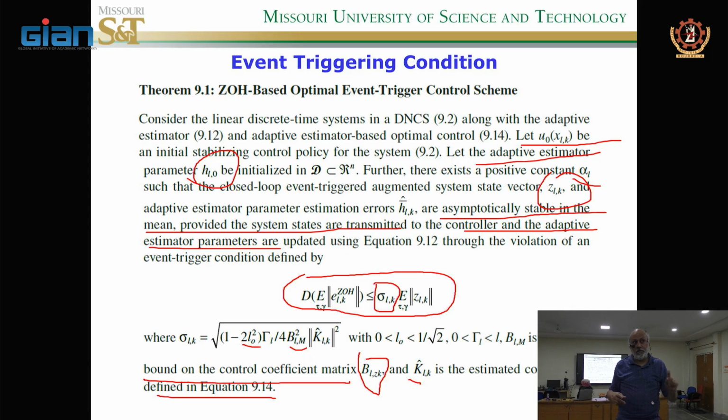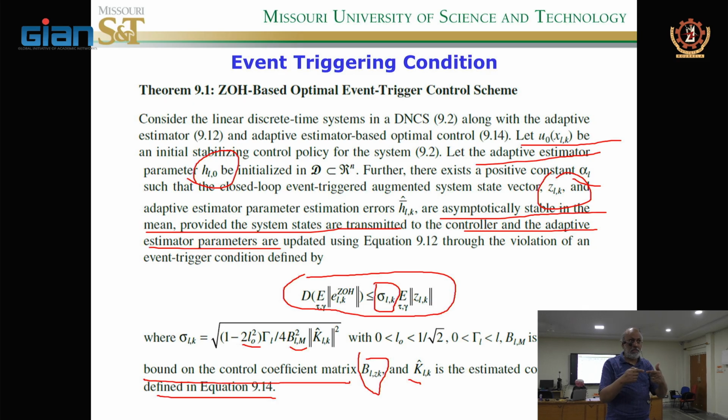But the CAN bus uses the CSMA-CD protocol. Now it's called CSMA-CA. CD is collision detection, and CA stands for collision avoidance. You want to avoid the collision, because whenever there's a communication going on, another node starts sending a signal, it collides, and then both of them back off. They found out the performance was going down.